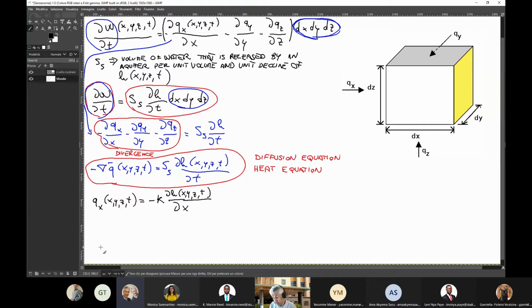So the change in hydraulic head in the right-hand side along the X direction regulates the flow in the X direction, which is placed here on the left-hand side. So you have a flow QX, which is originated by a change in hydraulic head in the same direction.